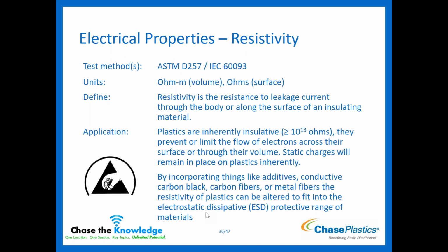If you've ever had one of those little slides that kids play on, and you walk over and there's a lot of static flying around, you touch it, it's the static charges on that surface, you get a zap. That's what this means in real life. Although plastics are inherently insulative, we can add things to adjust that. We could add additives, sometimes we'll do coatings, you could add conductive carbon black, carbon fibers, different metal fibers, because metals are conductive and will conduct electricity a lot easier. We can add those to our plastics to get them to start to conduct and reach different resistivity levels for different types of applications.